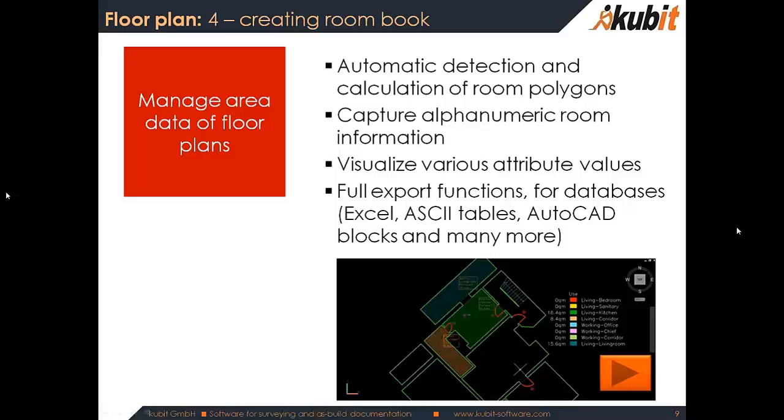That was the short introduction to floor plans. Section plans are generated in a similar way. You create vertical slices, you draw the building structure also with polygon fitting, and complete and annotate it with AutoCAD tools and PointSense Building commands.